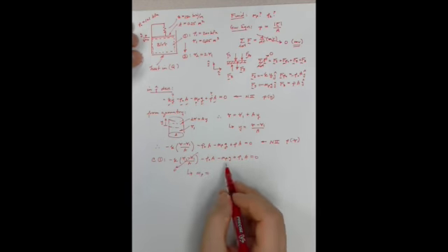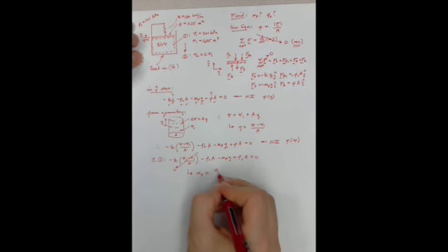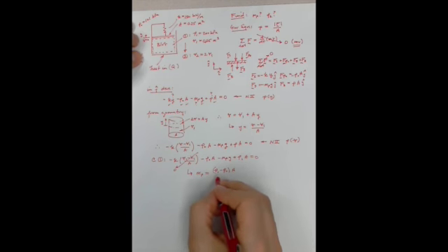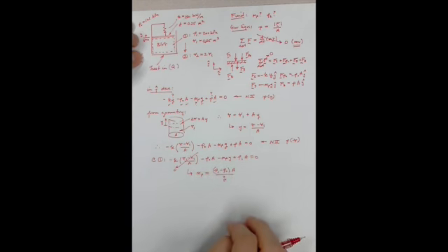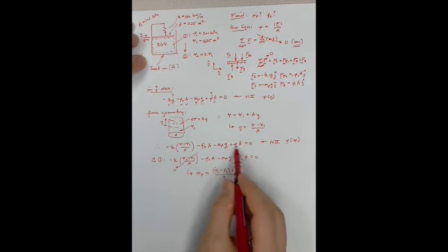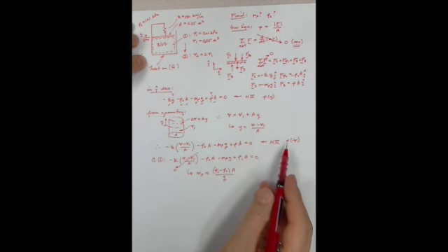So if I solve this for the mass of the piston, I bring it over to the other side of the equation, I'm going to get P1 minus P naught times A over g. Everything here is known, and I can easily compute that. We'll do it in a second. So if the mass of the piston is known, that means in this equation up here, everything except for P and V, which are both variables, are known.